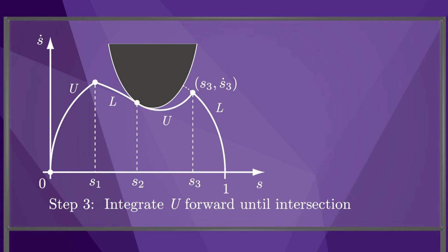In the figure shown, the algorithm completes with 3 switching points, and the time-optimal time scaling consists of maximum acceleration until s1, followed by minimum acceleration until s2, followed by maximum acceleration until s3, followed by minimum acceleration to bring the robot to rest. This time scaling keeps the velocity as high as possible at all points on the path while assuring the trajectory is feasible for the actuators.